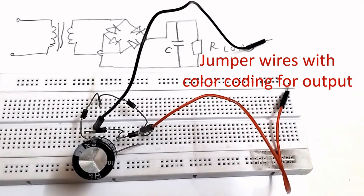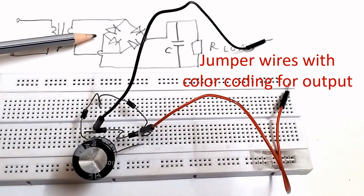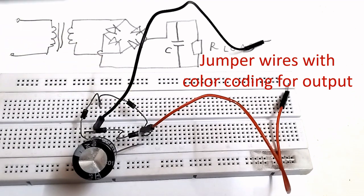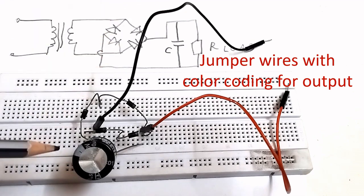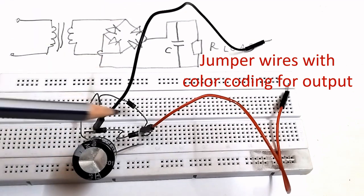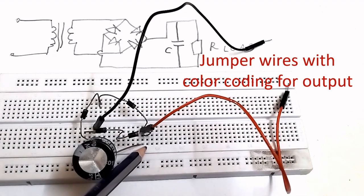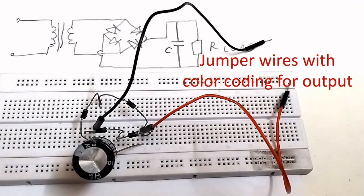Now I have connected 2 jumper wires, one corresponding to the negative terminal here. This is the negative terminal, and another corresponding to the positive terminal. I have given color coding also, black for negative, which comes from the negative of the capacitor, and the positive one which will be corresponding to the positive pole of the capacitor as well. So this is the output of the power supply which I connect to a load, whatever circuit you are going to drive with this. The final part I will have to connect is the transformer.